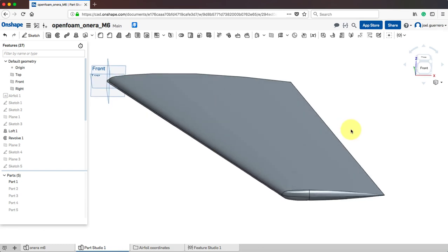This was the geometry generation, and starting from the next video we're going to export this one to STL, and then we're going to do the meshing. But before doing the mesh, I will show you a few things about the STL that you need to have in mind when exporting the STL that you're going to use with snappyHexMesh or CSMesh. We're going to use CSMesh.